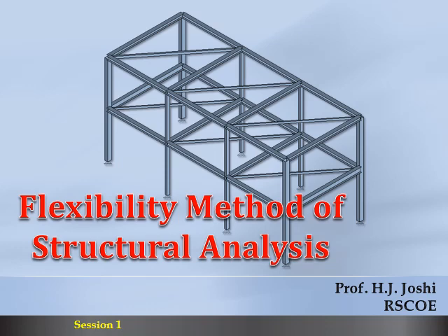Hello friends, today we are going to discuss indeterminate structural analysis by flexibility method. Basically, all indeterminate classical elastic methods can be categorized under two. One is force method or flexibility method, in which the forces are the primary unknowns, while the second is displacement methods, in which the displacements are our primary unknowns.